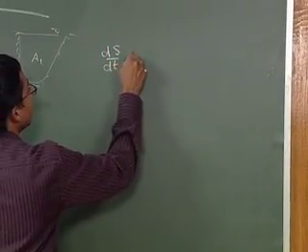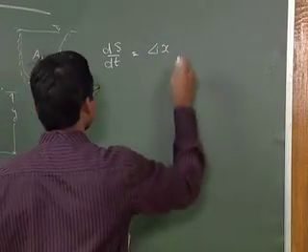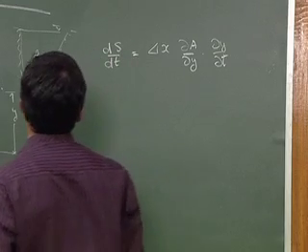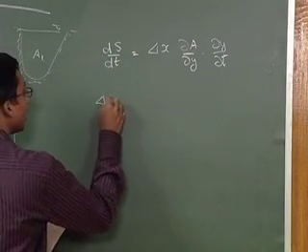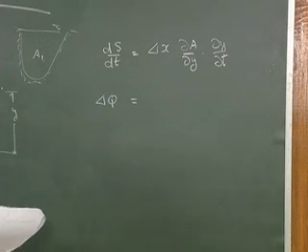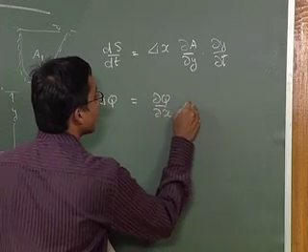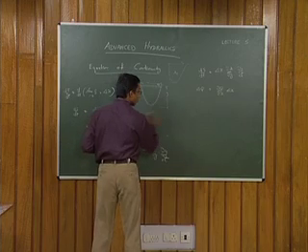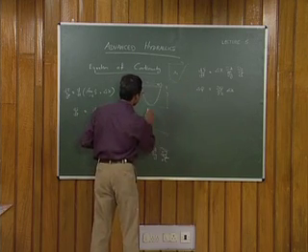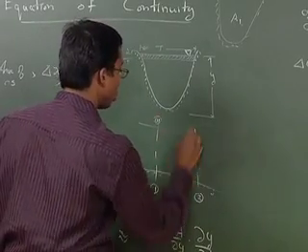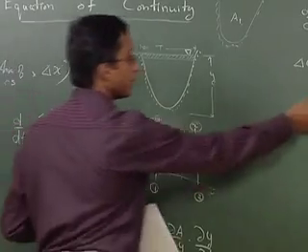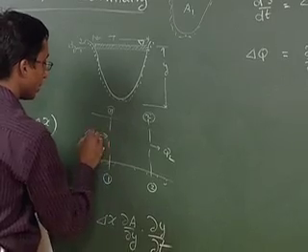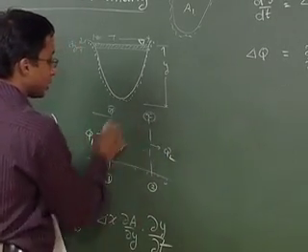So, continue the formulations. You got ds by dt is equal to delta x dou A by dou y into dou y by dou t. You also have seen that delta q can be given as dou q by dou x into delta x. So, in the channel stretch for section 1 and section 2, we have suggested, say, if Q2 is the discharge from this portion, Q1 the discharge entering here, ds by dt is the change in storage between the two sections.